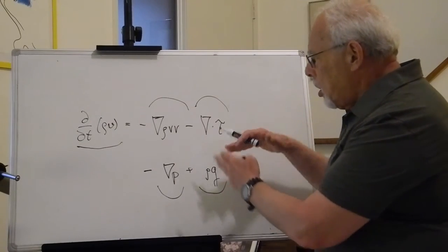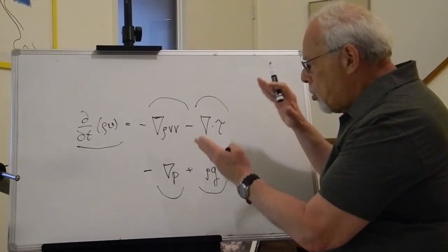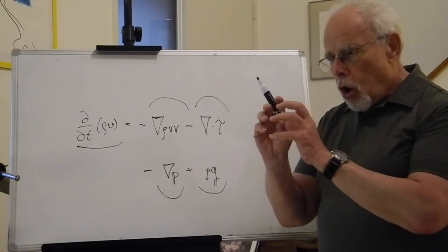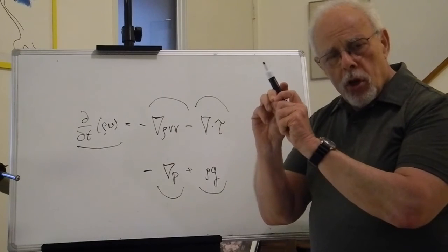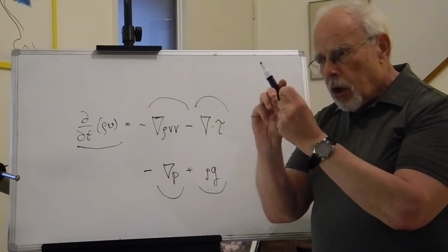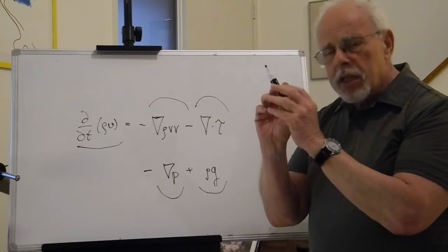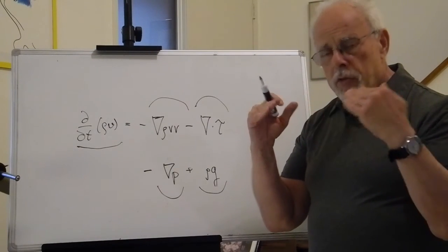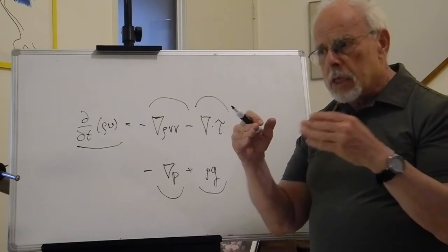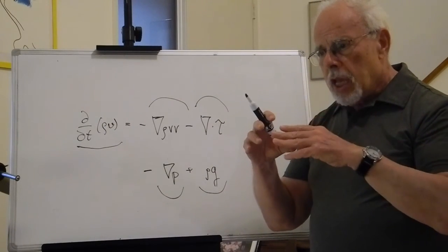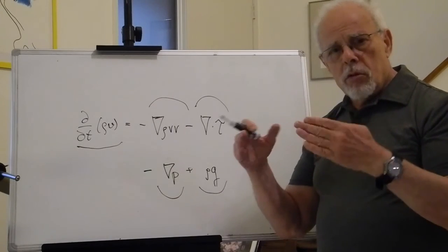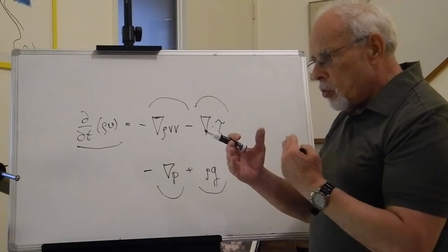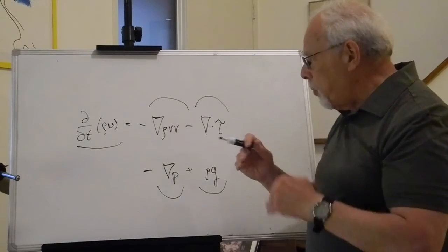Same equation, more concise form, that's the balance of momentum over a small unit of volume, expressed in Cartesian coordinates. One of the advantages of tensor calculus is that the expressions are the same in all systems of coordinates. And it's easy to transform from one to the other.